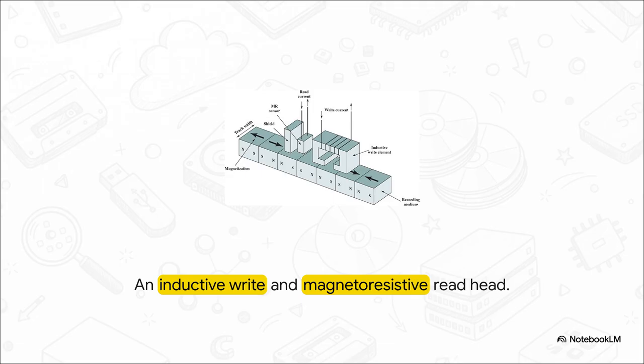To write data, electric pulses are sent to the write head, which is basically a tiny electromagnet. This creates a magnetic field across a tiny gap, which then magnetizes a small area of the platter zipping beneath it. Positive and negative currents create different magnetic patterns. Boom, there are our ones and zeros. To read it back, modern drives use a completely separate hypersensitive magnetoresistive, or MR, sensor. That sensor detects those magnetic changes as electrical resistance, converting them back into voltage signals.